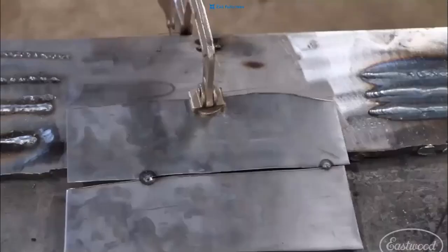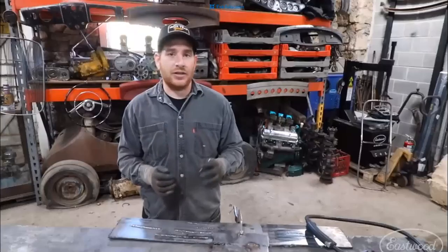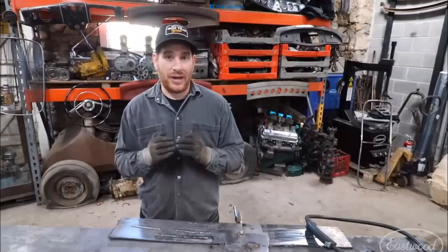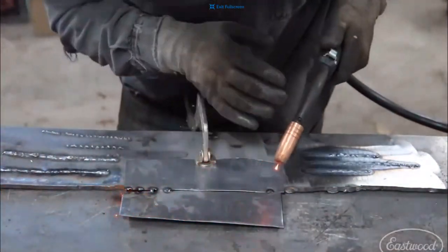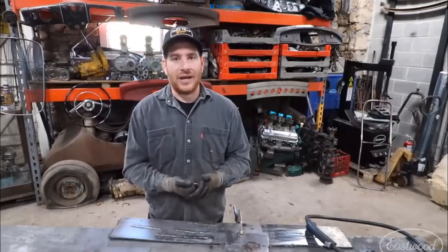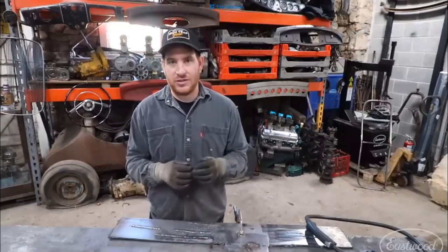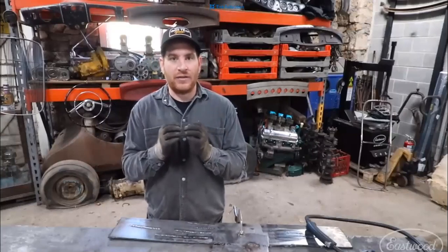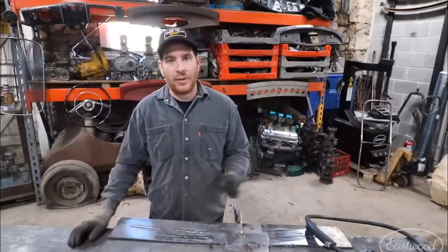If you have a gap where you have a jagged edge that's cut and it goes from being too tight to open to tight again, you may have issues where you may set the welder up for a good fit up of your panel, and when you go to an area that has a big gap, it may just blow through. The other reason is that there's nothing holding the panel from the back side, and you may blow through the panel because as soon as it touches it, the two edges that are cut, the gap, are going to burn away very quickly, and they'll just blow a hole in the panel.